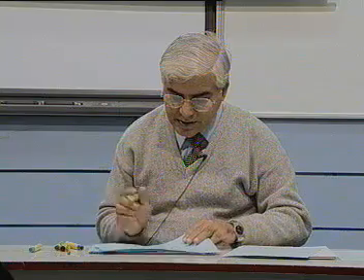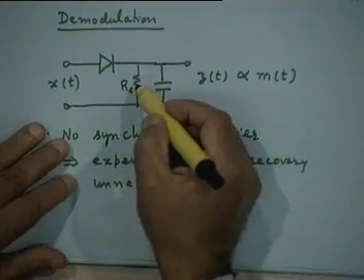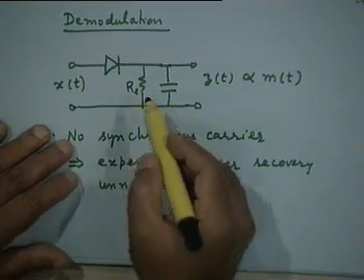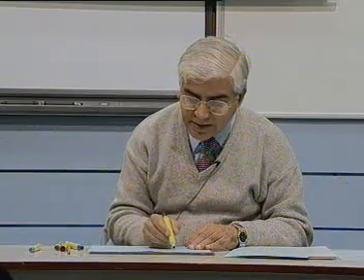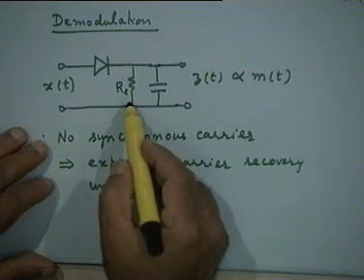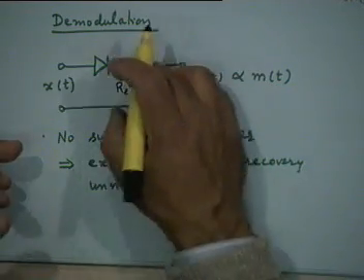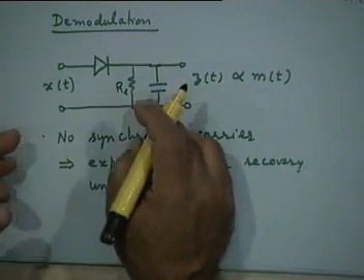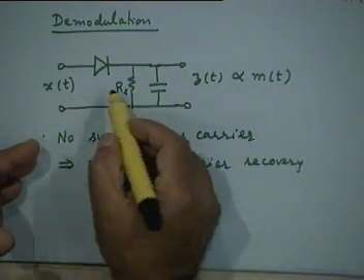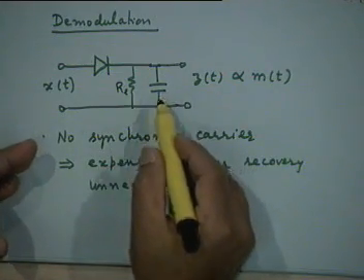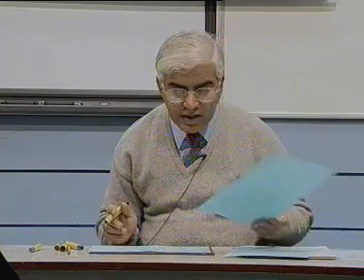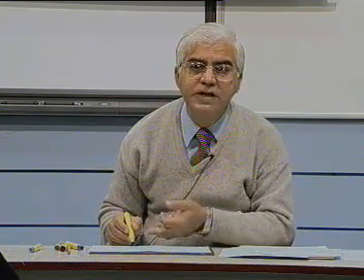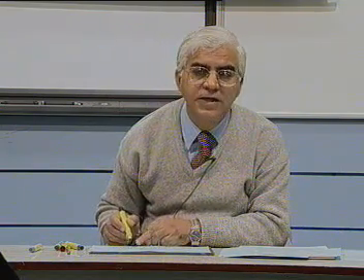So what is the RL? RL is this load resistance that I have talked about. Then why are we saying that RL is far greater than RS plus RF? I just explained, because if you assume that, then this would not come into the picture of the charging time constant. This will be so high that the charging current will hardly flow through this resistance. Most of the current will be used to charge up the capacitor, right? We don't have to worry about the value of RL in calculating the charging time constant.